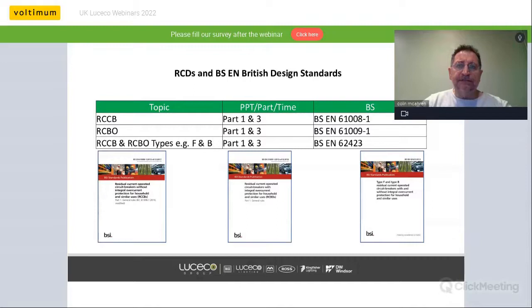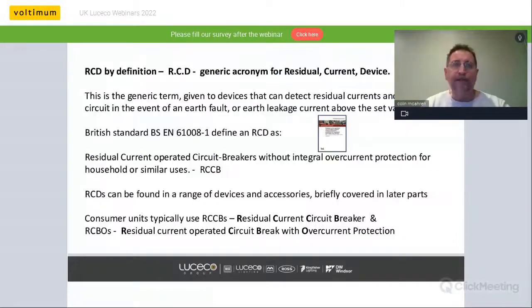The slide shows the standards we'll be more familiar with in terms of the 61008, 61009 standards, and the new, recently introduced standard which covers your F and your B type RCD.